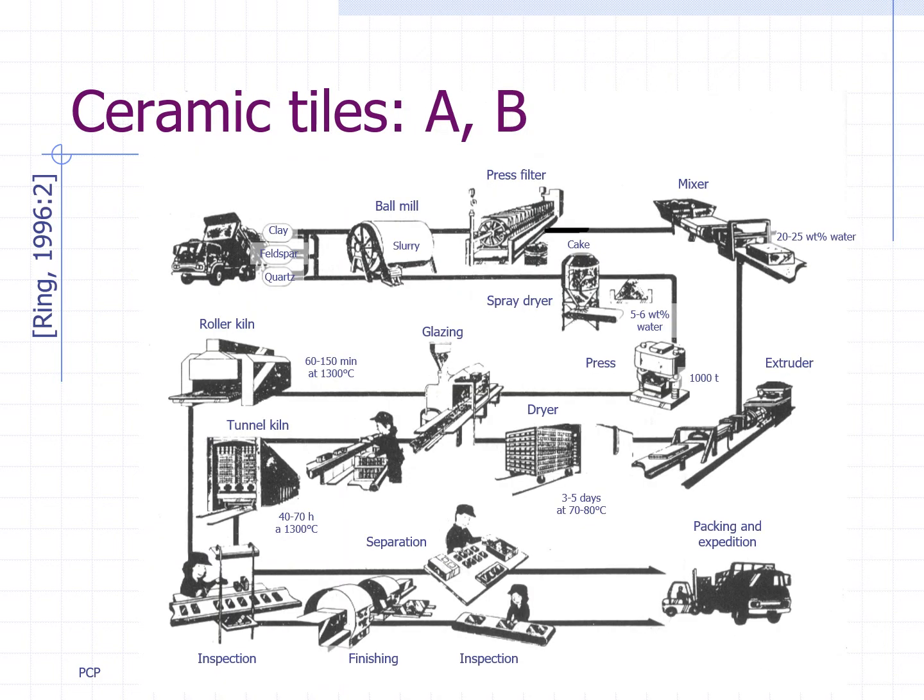A more pictographic representation of concurrent ways to fabricate ceramic tiles is shown here. In this case, a so-called triaxial ceramic that is made of clay, feldspar, and quartz is first wet ball milled and then must follow one of two alternate ways. First, the powder slowly goes through a press filter presenting 20 to 25% water.